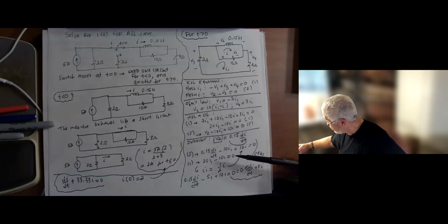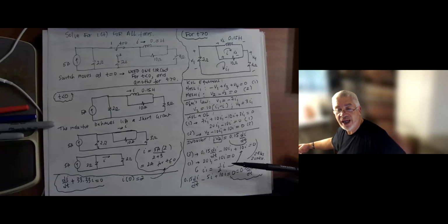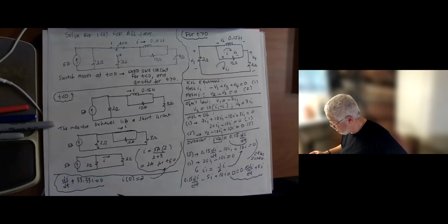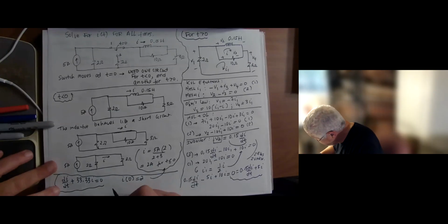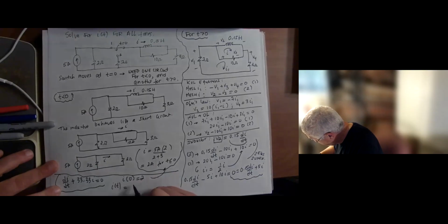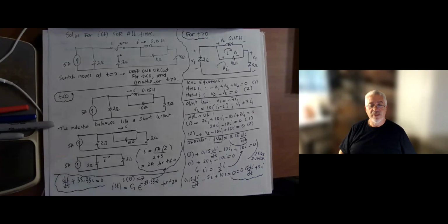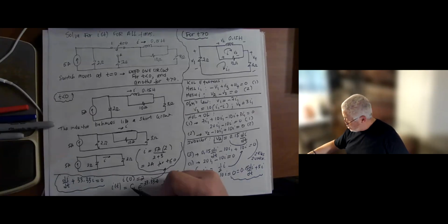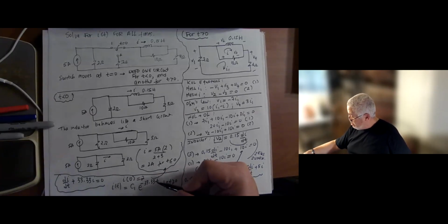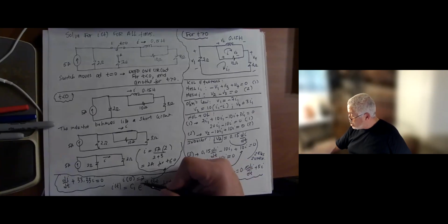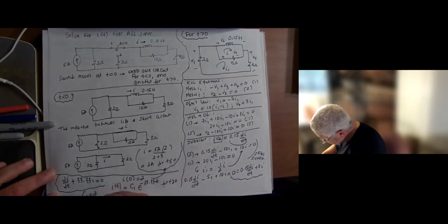and then I bring in the inductor relationship into those two equations, and then I use substitution to get a differential equation, which eventually leads me to the normalized system. So the solution to this is obviously some constant C1 e to the minus 33.33t for t greater than or equal to 0. That's the solution, where the value of C1 is going to be enforced at t equals 0. So C1 is going to be 2.